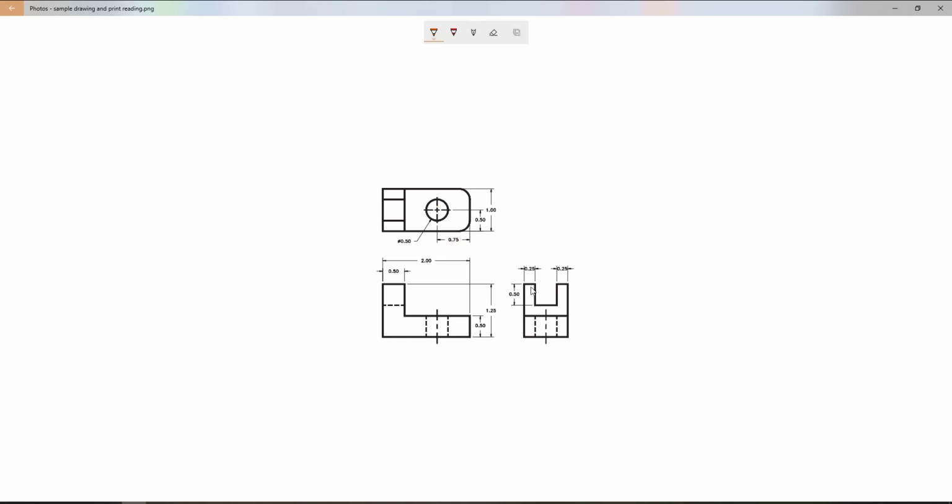And the slot also has a size, so it's a 1/4 inch and a 1/4 inch on each side, and a position a 1/2 inch down in that location. So each feature has to have a size and position. That is really important when you create the dimensions, but also when you're reading dimensions, you can see that some are dedicated to the location, some are dedicated to the physical object size itself.